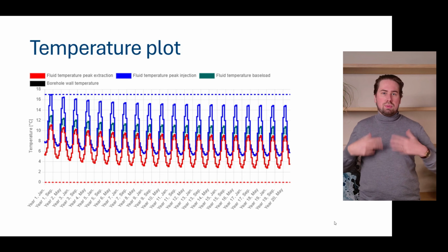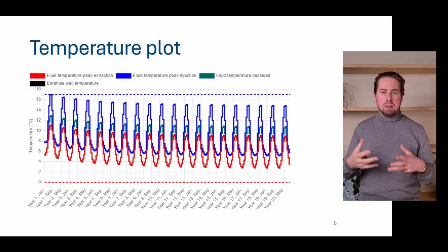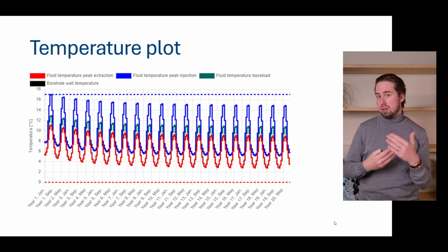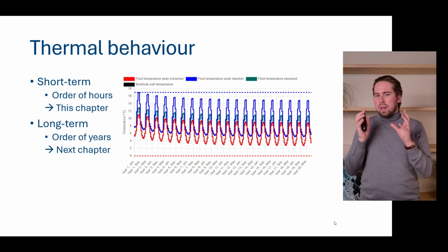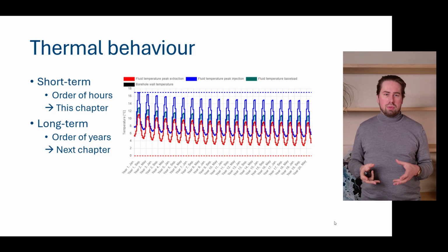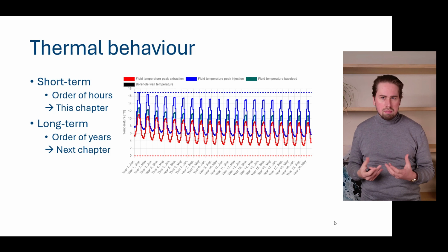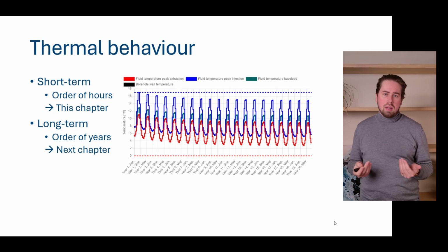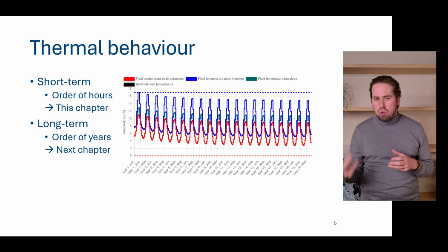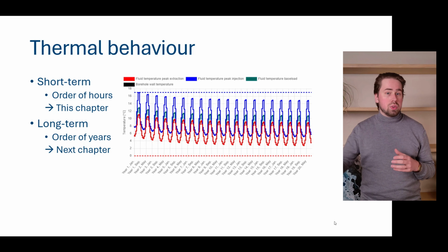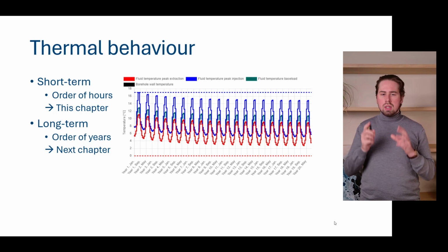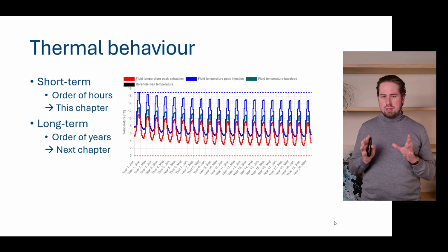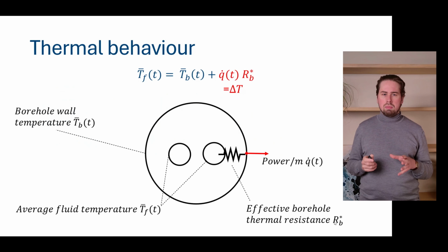And it's these fluid temperatures we're actually interested in because we're designing our borefield to stay within certain temperature limits. And that's how we can look at this thermal behavior. We can look at it from the short term in the order of hours, which is the content of this chapter, and on the long term, in the order of years or also seasons, which will be covered in the next chapter.